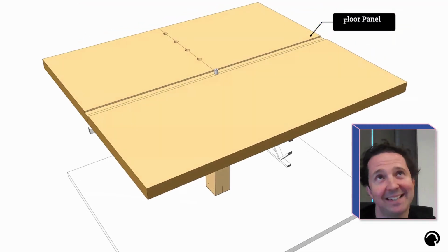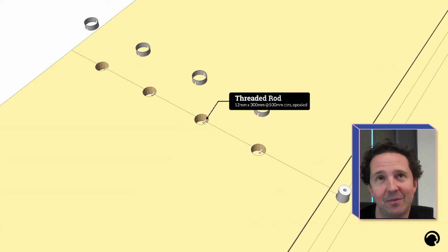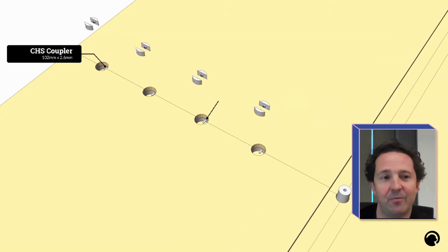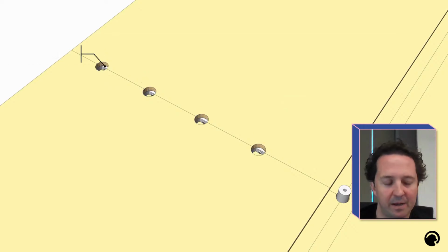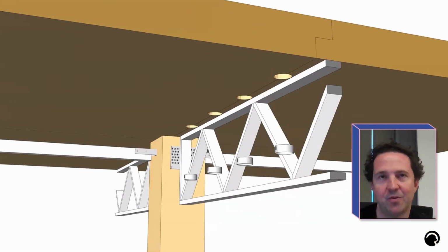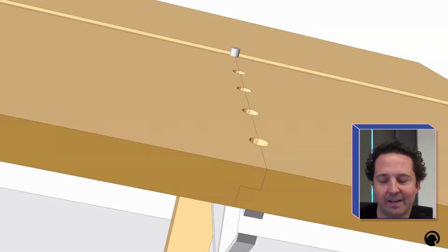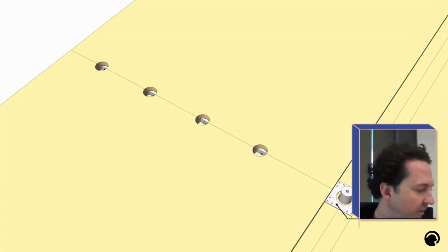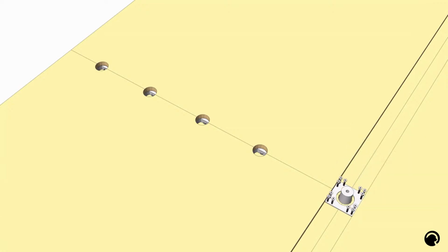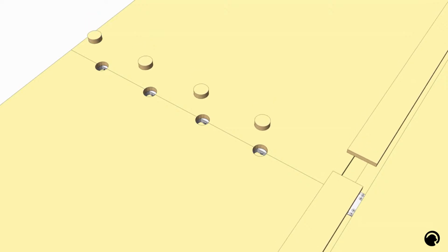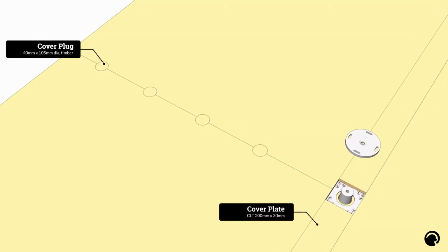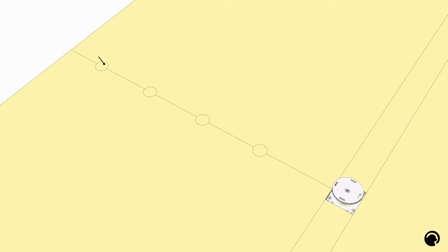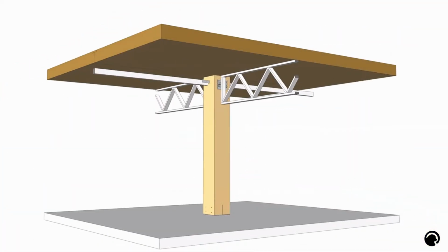But I think it's interesting that this kind of logic is, if you go down a DfMA route, a huge part of your contribution is how it's built, not what is built. As architects and engineers, we spend a lot of time maybe value engineering or changing the design to reduce costs. But actually, if we can think about how it's built and save on that installation time, you may not need to change the design, right?